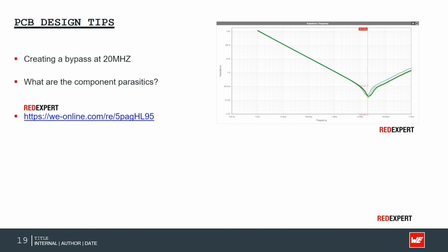In short, REDEXPERT is a searching tool of Würth Elektronik where the data of a big amount of components is collected. The nice add-on is that REDEXPERT is using measured data, therefore all the parasitics are included in the search. When looking at our case, using the slider and sorting on the lowest impedance, I'm able to find that the 150 nanofarad is an interesting value to use.